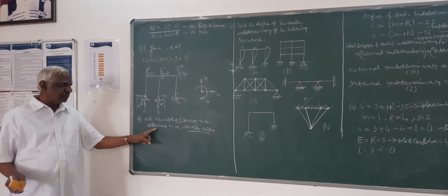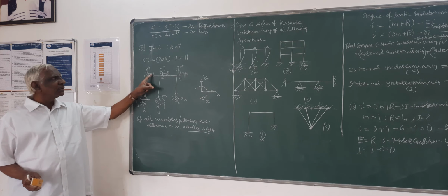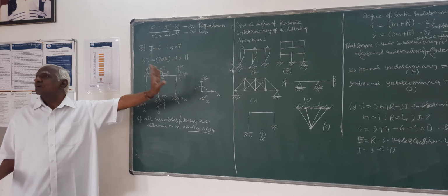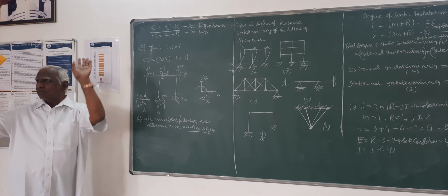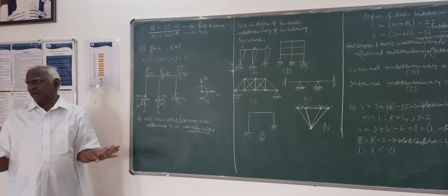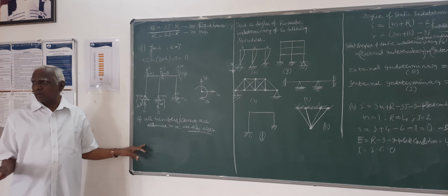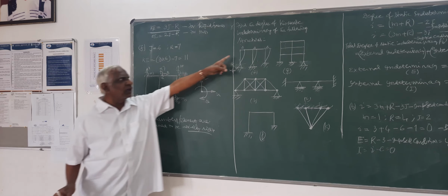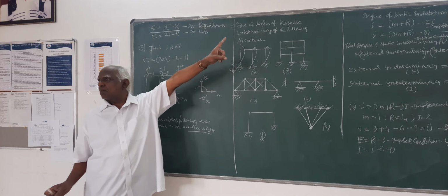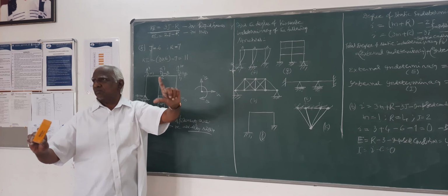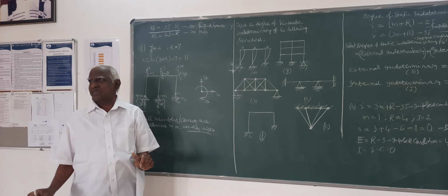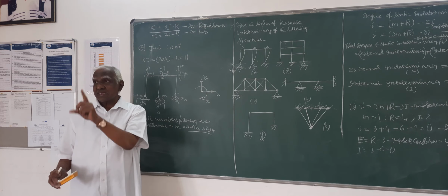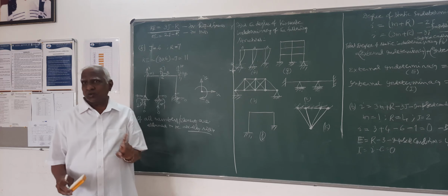If it is axially rigid, whatever motion is there, that is there of course. The other two horizontal motions will be the same. It cannot be different the moment you assume axially rigid. So I have to call it 3, 3, 3 only. They are moving by the same amount. There won't be any difference between left hand and right hand movements. The rigid body motion will be there. That is what you have to remember.